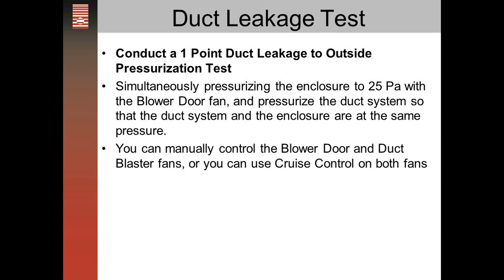So if you're doing a pressurization test, your test is going to start out with the duct under a negative pressure, and you want to go past -0 to +0, and then if it goes past +0, it'll start slowing down. So during a pressurization test, you would set it to +0.